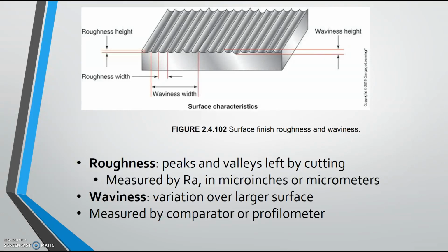That's because as the size gets larger, the potential for an error of form is going to be greater and greater because you are now looking at variation over a larger surface. So surface plates that are really big are going to have looser tolerances than smaller surface plates because we can reduce the variation when we are reducing the surface size.